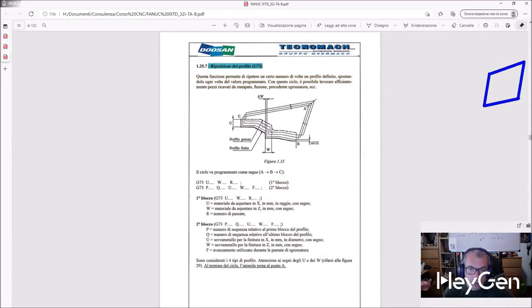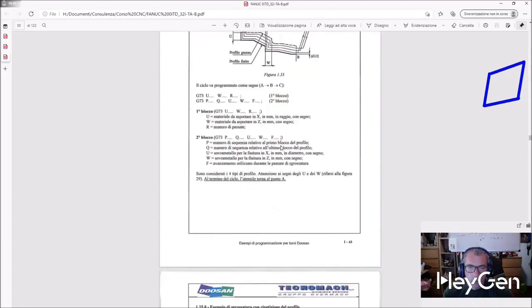You should rough them out in ISO to avoid unpleasant issues. So you have to work point by point and do the various roughing operations, meaning from X plus to X minus, and then for all diameters. Because with this macro, you can run into a lot of troubles. This is an example of the macro, so I'll leave you everything you need to study it, but I won't explain it to you. I've never used it. I've made quite a few molds in my life.